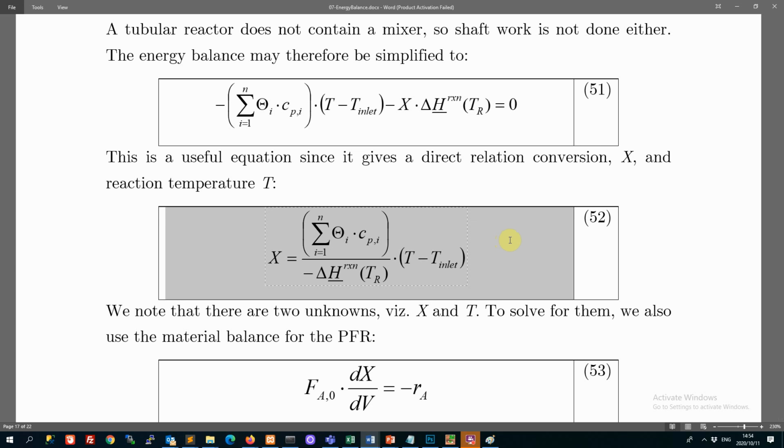It's telling us that for this set of species, for you to raise these species by this temperature, the only possible way you could have done that in the absence of other heat being added, with these heat capacities and this heat of reaction, the only way you could have gone from 100 to 200 is if you had accomplished that conversion. So this is an important relationship. It helps us understand the relationship between temperature and the achieved conversion.